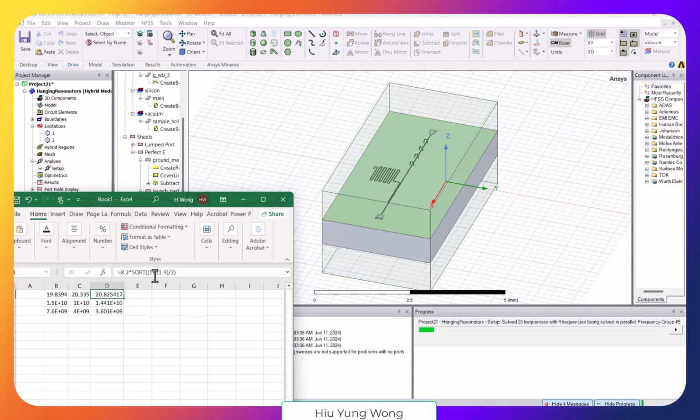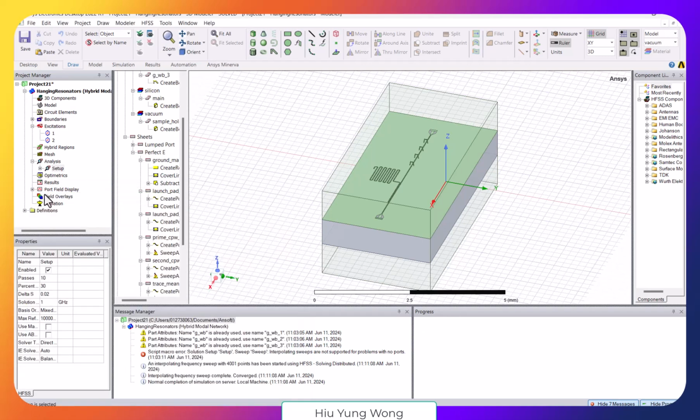But I try to correct with the dielectric constant. So that mode will correspond to 3.6 gigahertz, right? Because if you find the wavelength of 3.6 gigahertz in the vacuum, and then you divide it by the refractive index, right? And then divide it by 4, then you will get 8.2. Okay, so we have this now.